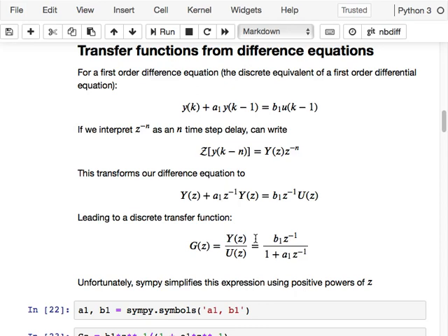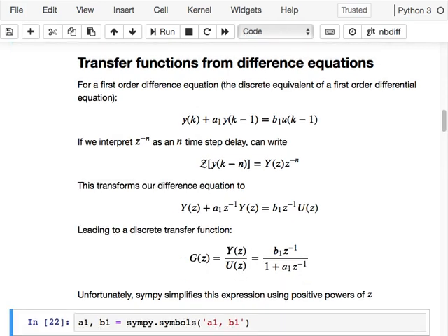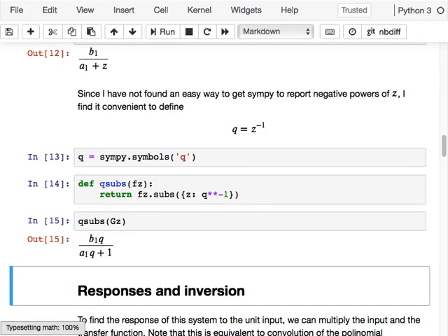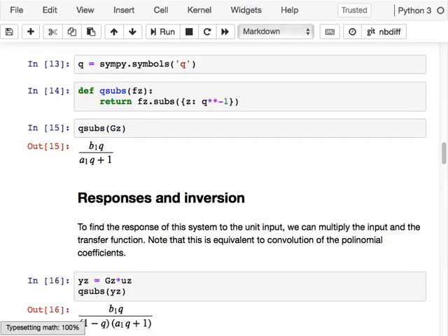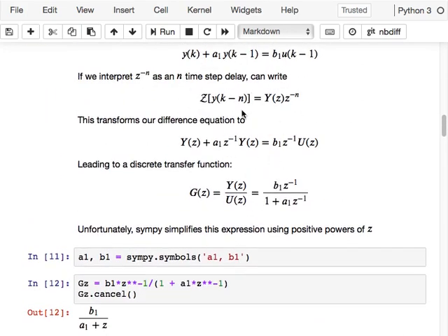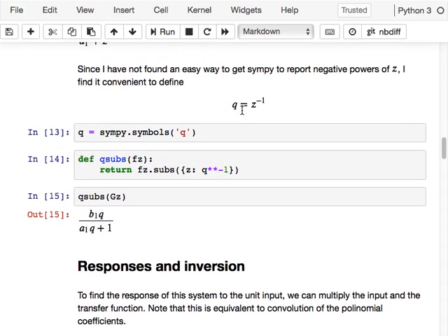I know how to do the Z transforms of signals, I know how to do the Z transform of processes, and everything else works exactly the same because the transfer functions have exactly the same idea, that they also are in series. We just multiply them. Multiplication basically corresponds to convolution, and we can do all of those manipulations relatively straightforwardly, going from the original time equations all the way through to these Z equations.